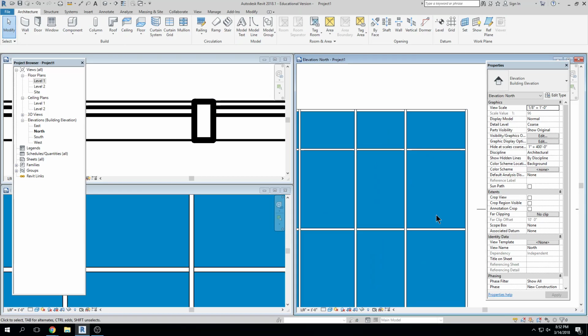So really, in actuality, when you're designing this curtain wall system and you're drawing it out, the storefront is generating as a wall, and the wall has these curtain grids that occur at every certain distance, whatever you define, 5 feet maximum or whatever. And then the wall system itself assigns a mullion to each of those curtain grids, vertically and horizontally, okay? And then it fills in a panel. So you have the whole system, the curtain grid, the mullion, and then the panel that goes in, right? So we have a lot of working parts here.